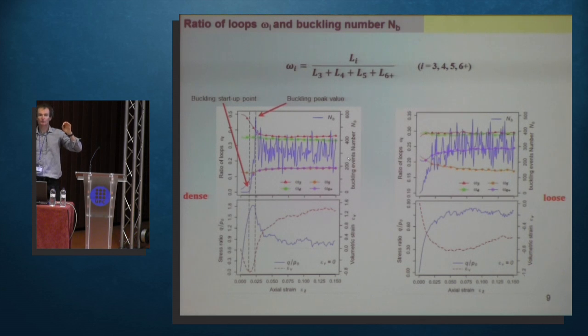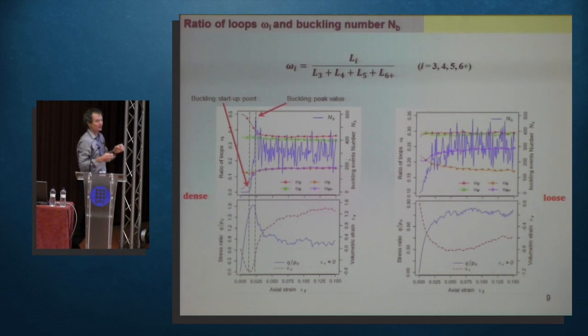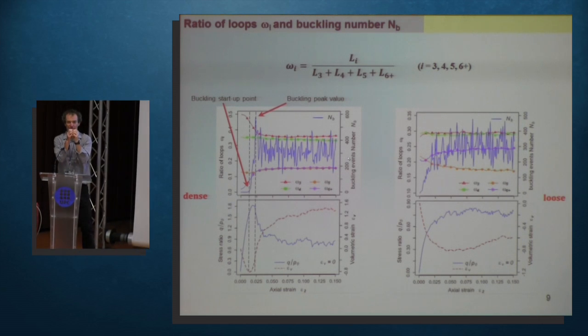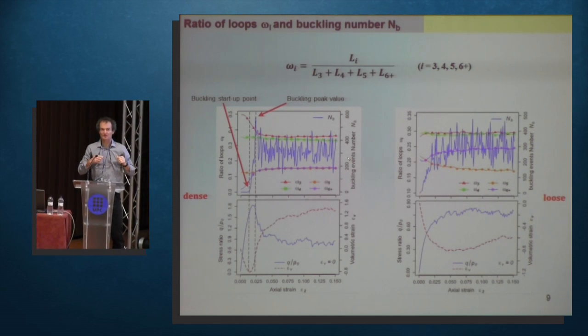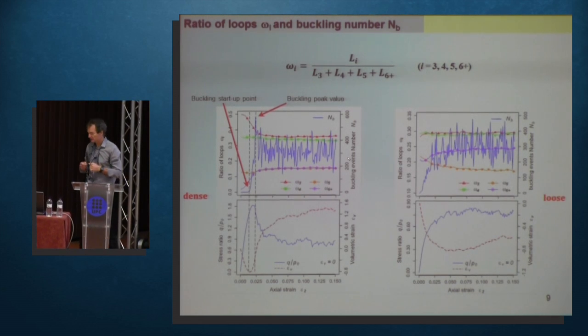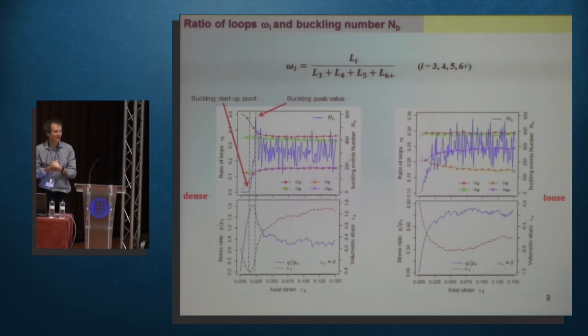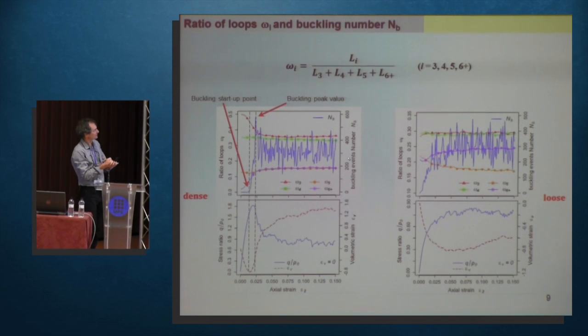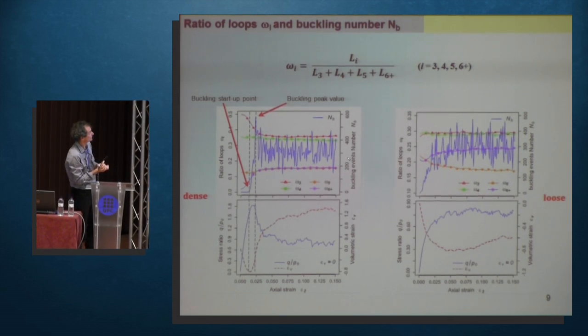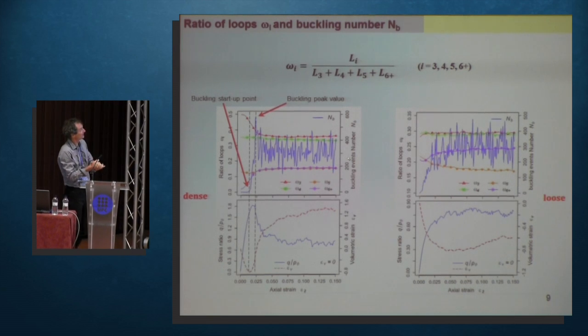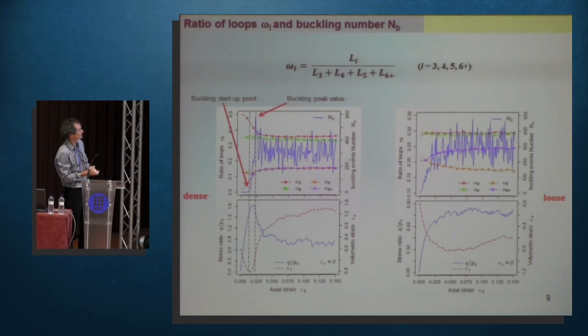So starting from a dense specimen, the very dense clusters containing 3 grains are decreasing, and on the contrary, the number of loose patterns containing 6 or more grains is increasing, and the loops containing 4 or 5 grains are more or less constant.